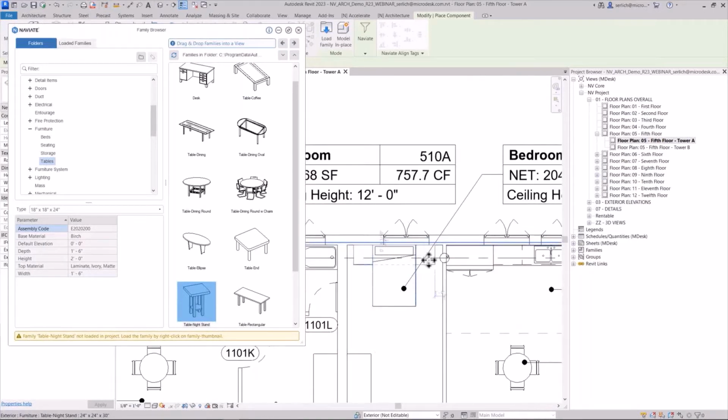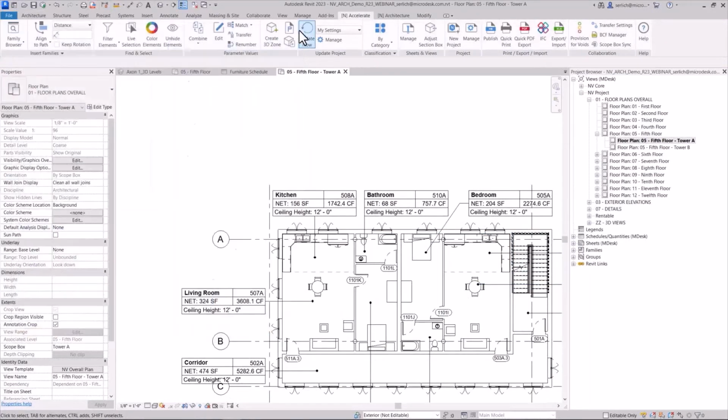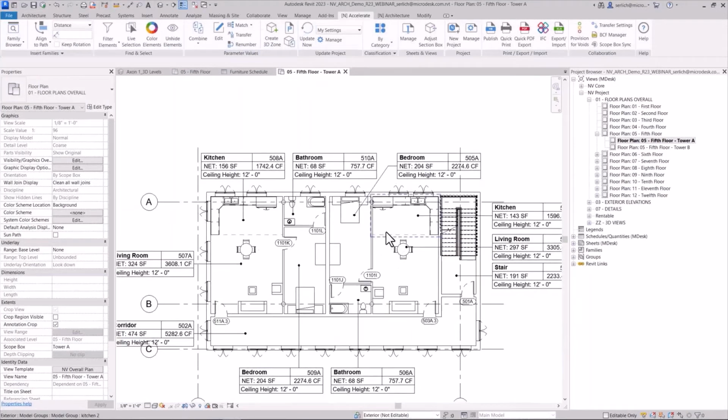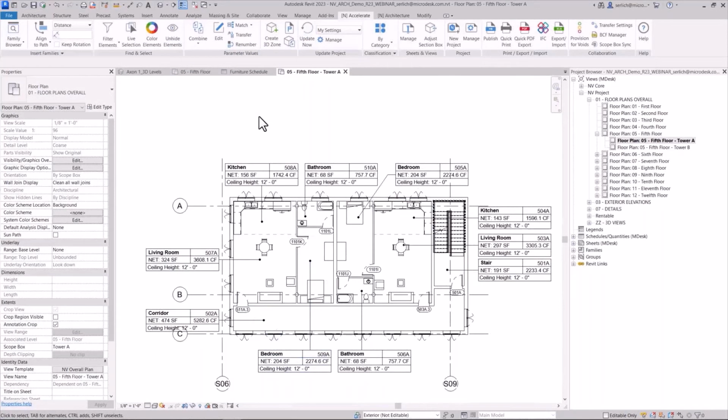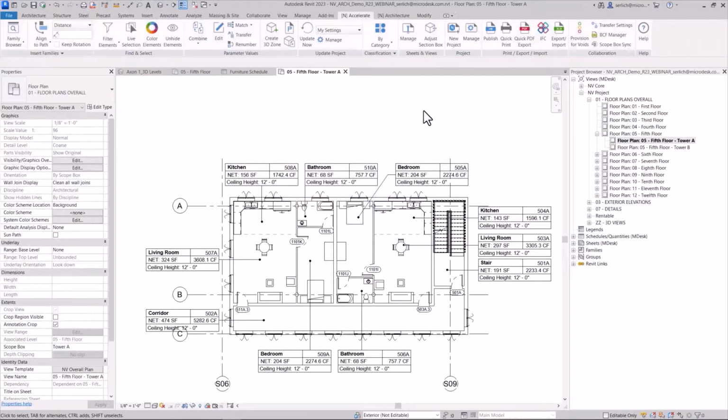And one last element. So now that we've placed everything to design our rooms, we want to work on getting data into those families. Specifically in this example, I want to push my room number and name into the family so I can schedule each family and group them to the room that they're located in.